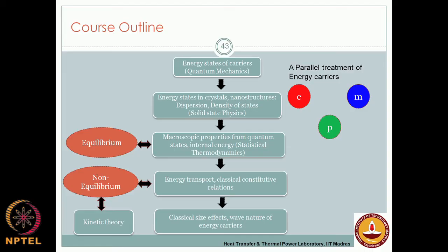So, then how do we look at non-equilibrium, that is the transport of heat, for example. For that, we will look at energy transport through non-equilibrium phenomena by solving the particle nature of energy carriers, say the Boltzmann transport equation. In parallel, we will also look at some hand-waving approach using kinetic theory, and we will show that using the particle-based sub-continuum Boltzmann transport equation, we can take moments and therefore derive the macro scale equations.